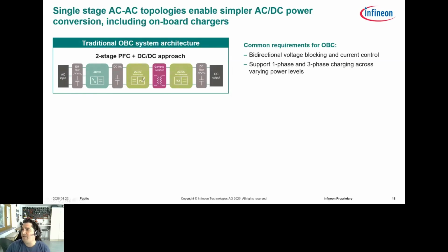the part of the world you're at. But here, we want to create something high frequency because you want to use a very small transformer, maybe even planar magnetic. So here we're talking about hundreds of kilohertz. Then you're going to have a rectifier, and then your DC filter and the output.